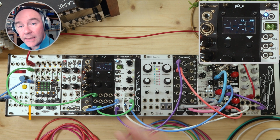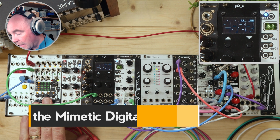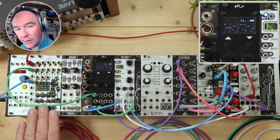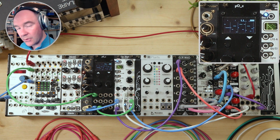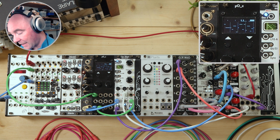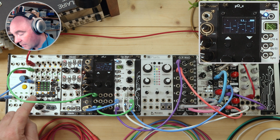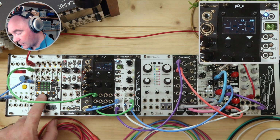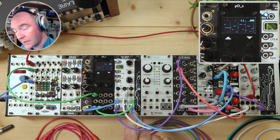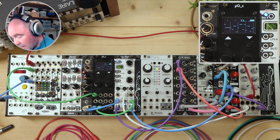Let's look at using a sequencer like the Mimetic Digitalis. The Mimetic Digitalis is a 4-channel, 16-step grid sequencer, and a grid sequencer means it doesn't just move linearly through notes, it actually can cycle between different rows of notes, and the rows are organized in groups of 4. So we're going to use sequencer 1 here for oscillator 1 through quantiser A, and sequencer 2 through oscillator 2 through quantiser B. So let's get patching.